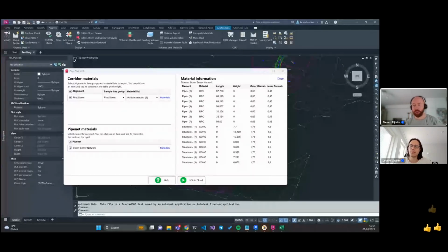Plugin for MEP, does it work for building? If you mean MEP data in Revit, you can export that just like normal construction data. You just have to be a bit careful in how it's mapped and what functional unit it uses. Because if we, for example, have EPDs for MEP data, they're generally reported in really strict functional units. A piece of heavy equipment might be reported in units, while plumbing or ducting is reported in linear meters, for ducting or cables, for example. So it does work, but MEP works slightly differently if we're working with MEP BIM models at least.